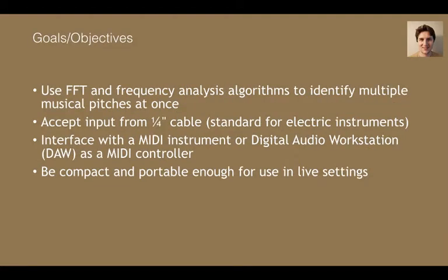What we wanted to accomplish here was to use the fast Fourier transform and frequency analysis algorithms to identify multiple musical pitches at once. We'd be able to accept input from quarter-inch cable, which is standard for electric instruments like guitars, basses, and most synthesizers. And we want to be able to interface with a MIDI instrument or a digital audio workstation, DAW for short, as a MIDI controller. And finally, we want it to be compact and portable enough for use in live settings.